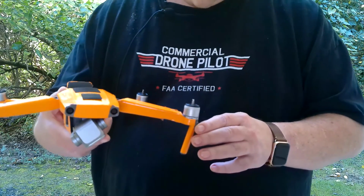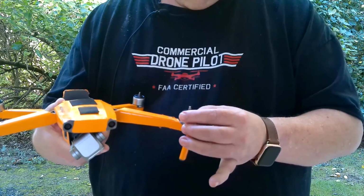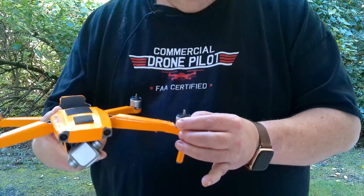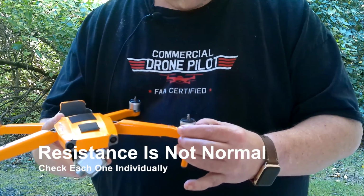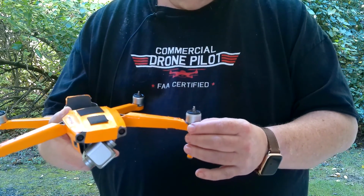So just do a visual inspection and turn the rotor with your fingers. Make sure that it moves freely, and as the holes pass over the housing, just check for the presence of any debris or dirt that might be present.